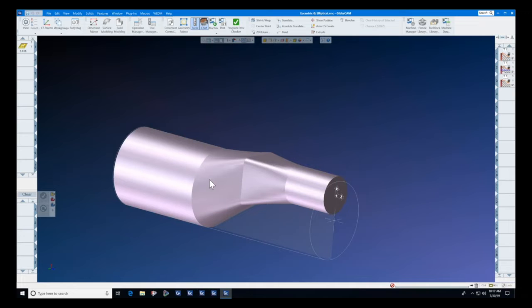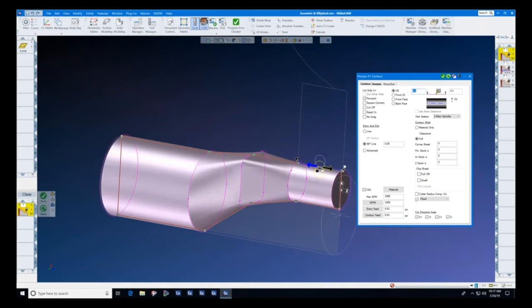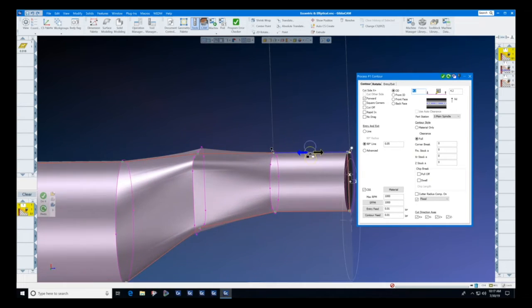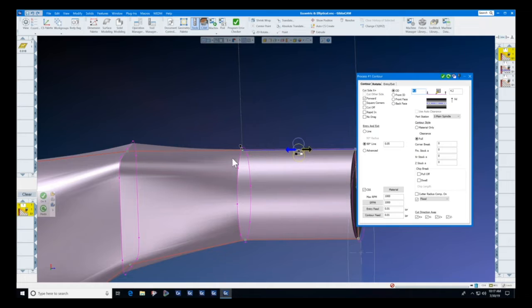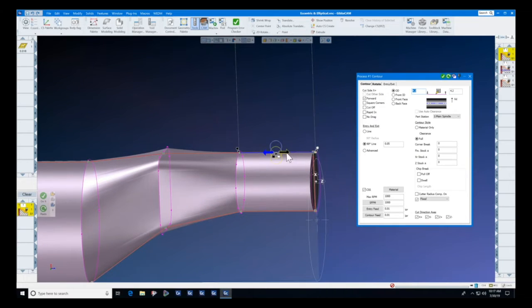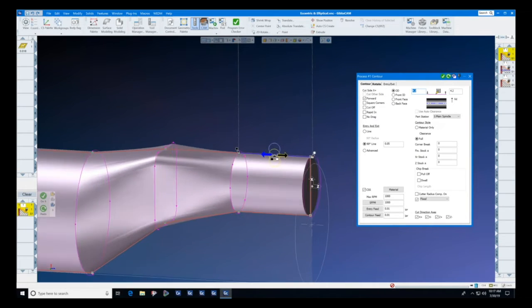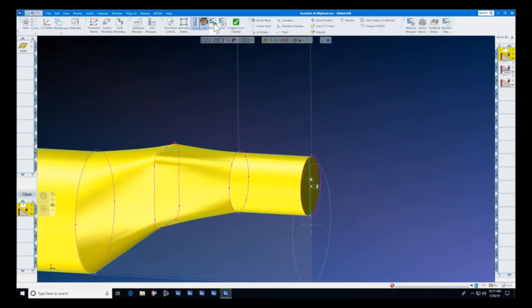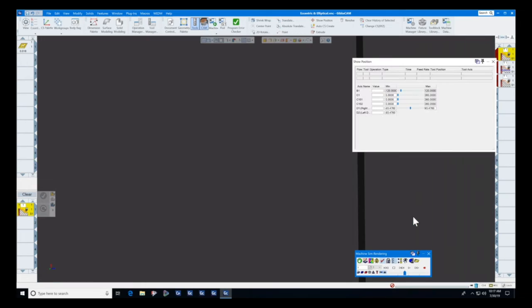And then the next section, elliptical section, which starts as a square and ends as a circle. We'll look at op 1. And as you can see on op 1, we simply selected a contour and we selected the geometry like we normally do with our machining markers. Let's look at op 1. Watch it run on this part, on this particular machine.